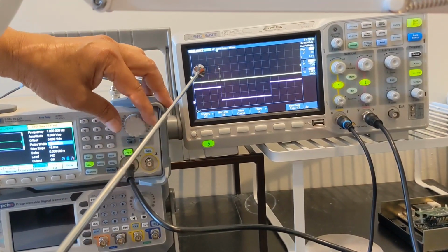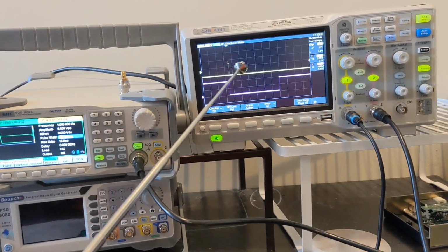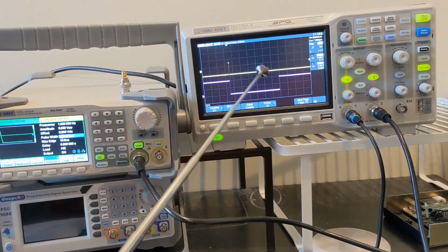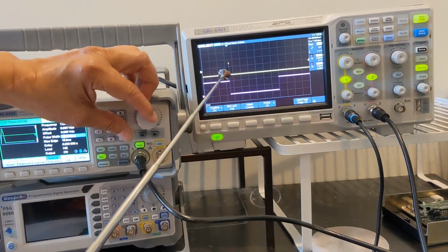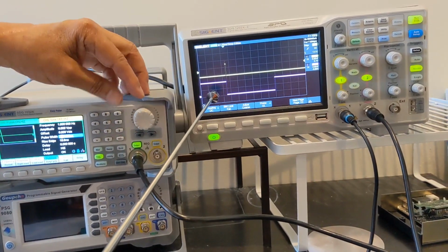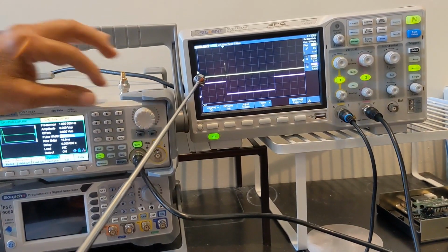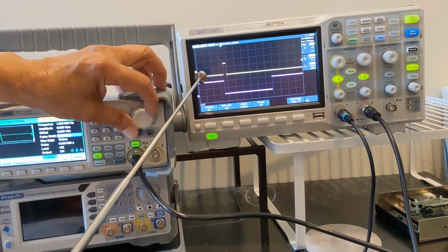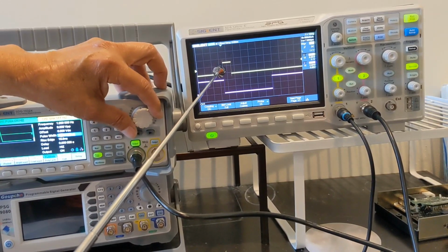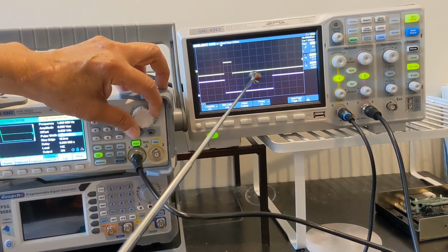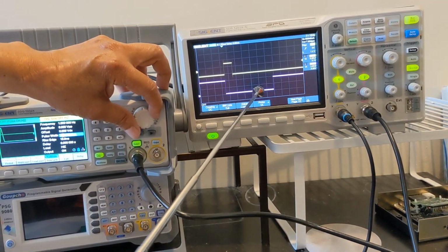Now we have 100 microseconds, and the output remained the same, because that's what you want, to be able to capture that event. I could see that it's beginning to show the width of the pulse. Now it's 200. You can see that the duration of the pulse continues increasing, but your output continues the same, because you really wanted to capture that length. At least you know the minimum length is going to be that.